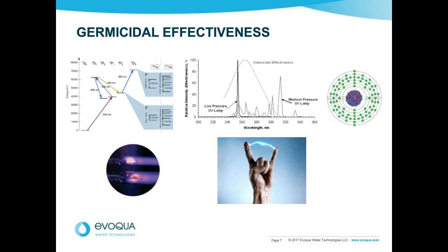What type of pretreatment do you prefer to see for drinking water from surface supplies? Well, we need to have some form of filtration. We see a lot of water sand filters being used very successfully in front of the UV equipment. The water sand uses a macro sand. So honestly, the more the better. It's well worth people investing in filtration to optimize the UV performance. The more you can raise the transmittance, the lower the power you'll need to use. So spend the money pre-treating the fluid generally.